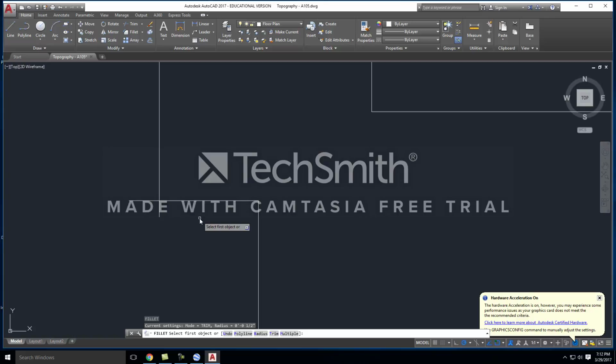So instead of selecting the first line, I'm going to hit R for radius, okay? I then hit enter. And then it says specify the fillet radius. Right now by default it's saying 1/2 inch. That's really like nothing. You probably won't even see that radius on the screen unless you really zoom in. But let's try putting in something that's fairly noticeable. We'll say like 2 feet. I go ahead and hit enter.